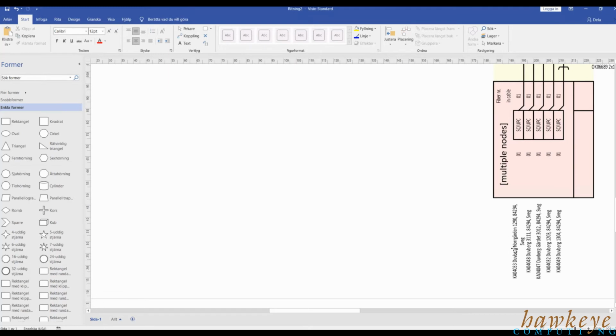Let's rotate the description of the first one and move it out. We can see that it's the one from our example, KA04033. We see the customer access node ID and the installation address. In a similar fashion, this single splice plan contains information about all the sockets we selected in the panel in the cross-connection form, namely the sockets number 61 to 78.